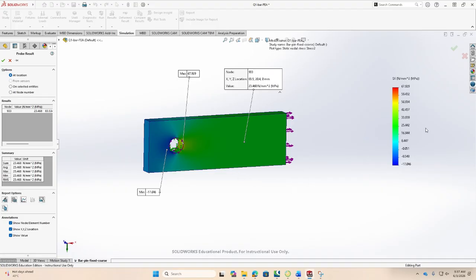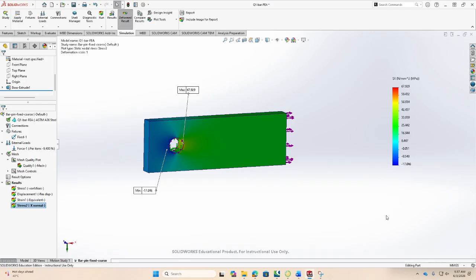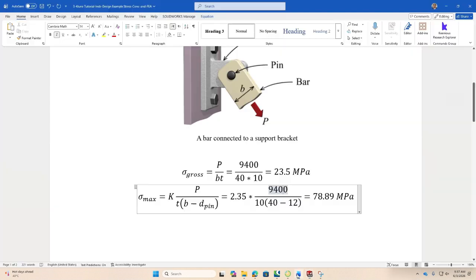So with this, then it means that, okay, by the way, we can always go back and check, because we already know the yield strength, so we can divide it with the yield strength to get the margin of safety. So if we were to calculate the margin of safety based on FEA, what we will do is we will use 67.929 from the FEA analysis. So I will just write it down for you guys.